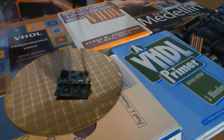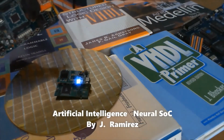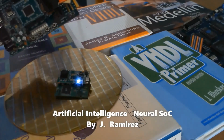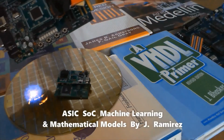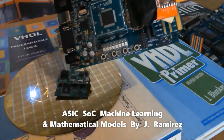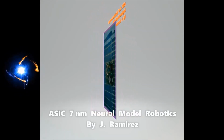Hierarchical entities, macrocells, have dependencies on one another. For example, one cell may contain another. One cell may compete with another for area on the chip. Or a critical timing path may pass through two macrocells such that there is a constraint on the sum of the path delays through the two cells.